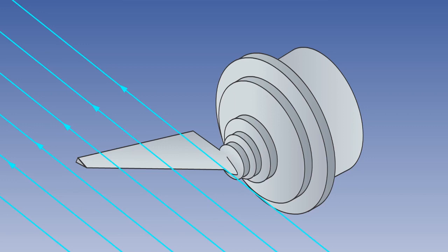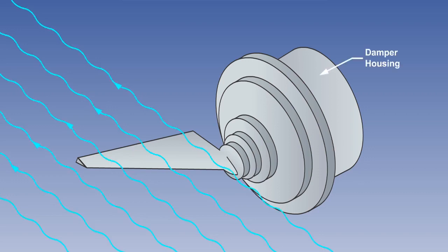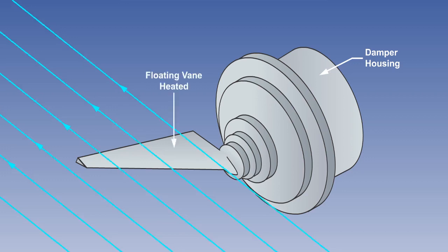As with the slotted probe type sensor, the electrical output can be used to position a pointer on an angle of attack indicator. Any destabilizing effects of turbulence are overcome by a viscous damper in the damping section of the transmitter. The angle of attack sensor also incorporates a vane heater, which prevents condensation and reduces changes in the damper fluid viscosity.